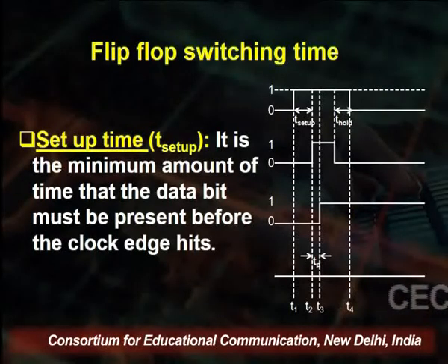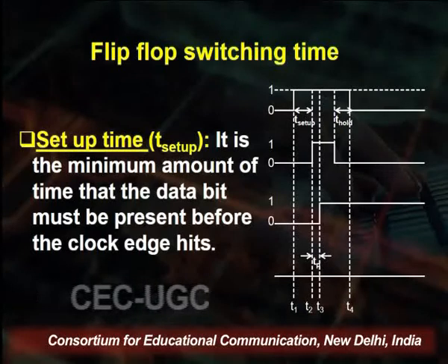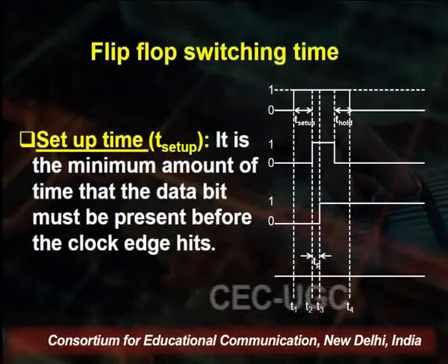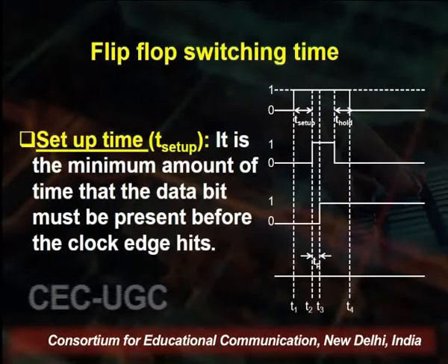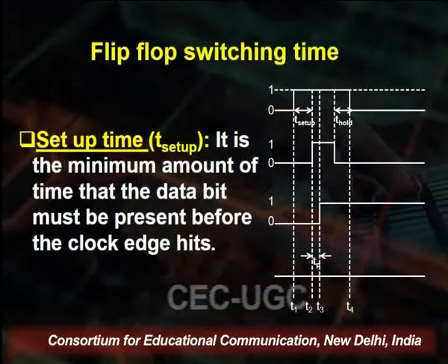That is the setup time. Setup time is defined as the minimum amount of time that the data bit should be present before the clock edge comes in. Typically, it is of the order of 5 nanoseconds, or for slower ones, it's 15 nanoseconds.